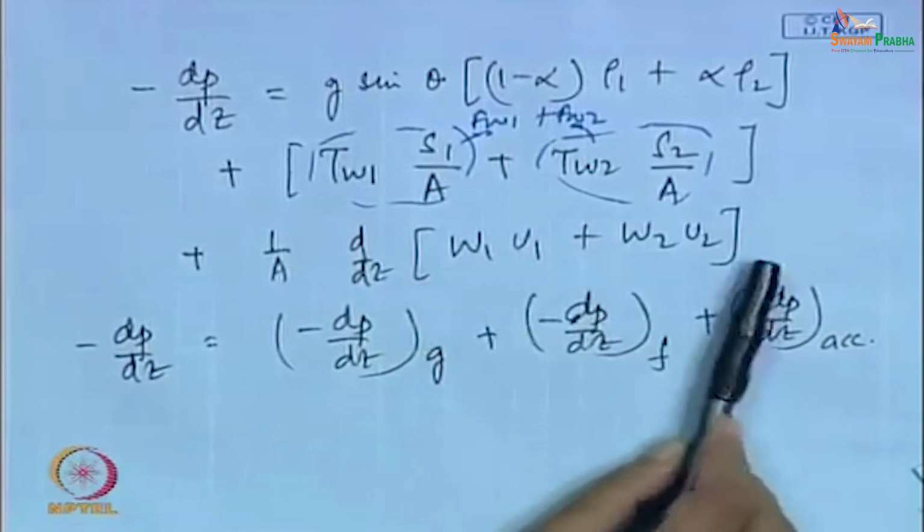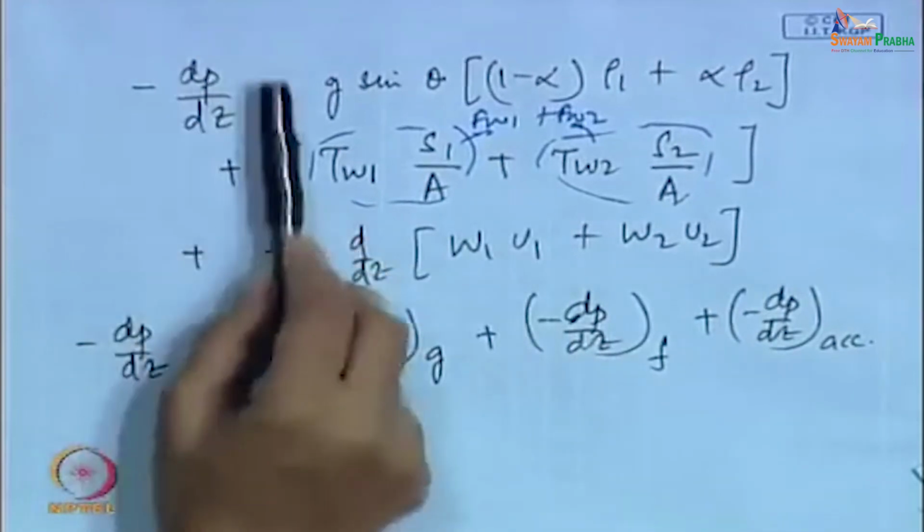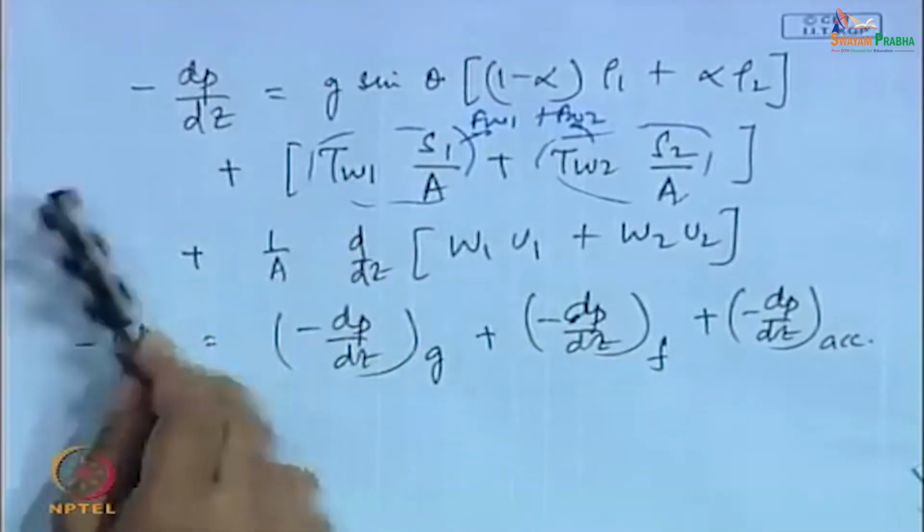Accordingly we have to write down this term, and then if we simplify the acceleration pressure gradient and incorporate it in the total pressure gradient, we would get the total expression comprising a denominator and a numerator, where the denominator will give us the choked flow condition for two phase flow under separated flow conditions, and the numerator will have three or four terms denoting the gravitational pressure gradient, the frictional pressure gradient, and the pressure gradient due to the area change and such other terms.